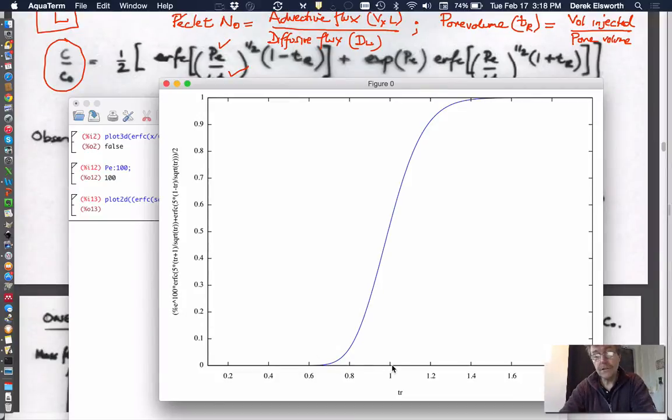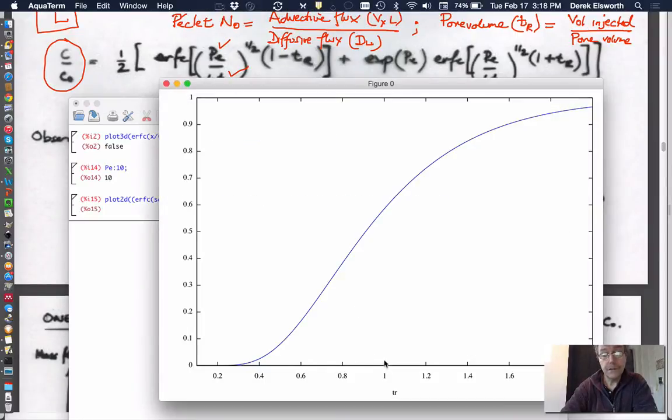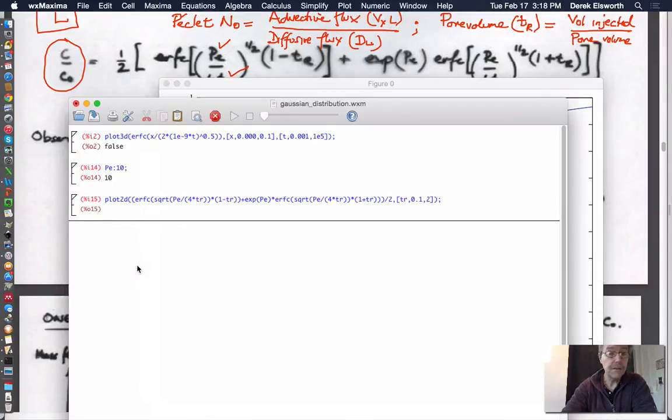So this is kind of the plug flow behavior. This is one pore volume. If you go up here, this is roughly 50%. Did you go across here? If we use progressively larger dispersion magnitudes, then we'd expect that it's going to flatten out, right? It should flatten out. So now this one pore volume, that's roughly the same. Actually, it's a bit higher. Looks like it's about 55%.